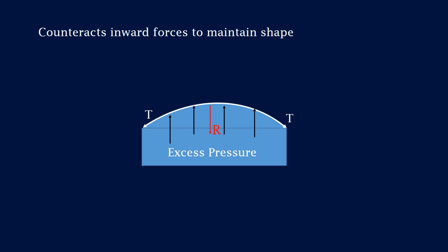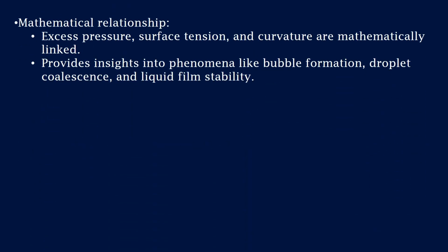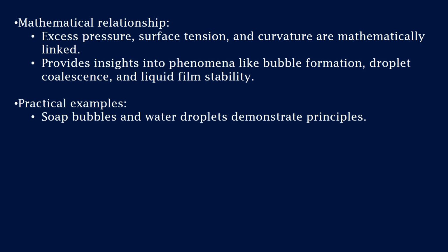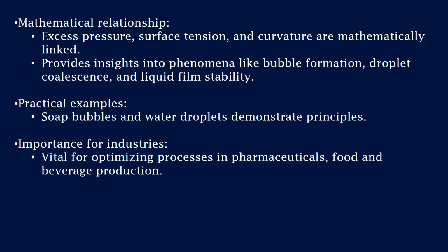However, in curved surfaces, such as drops or a bubble, surface tension causes an excess pressure inside compared to the surrounding medium. This excess pressure ensures that the drops and the bubble maintain their shape by counteracting the inward forces trying to collapse them. The relationship between the excess pressure, surface tension, and the curvature is mathematically described, providing insight into various phenomena like bubble formation, droplet coalescence, and stability of liquid films.